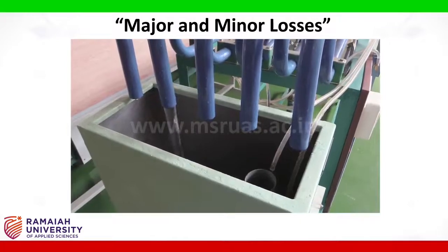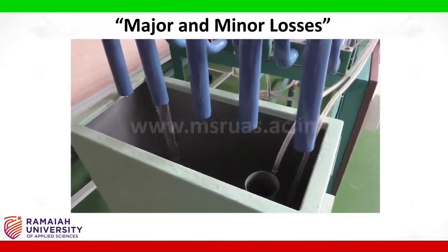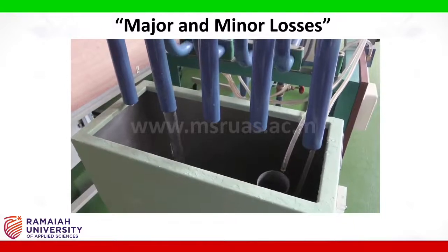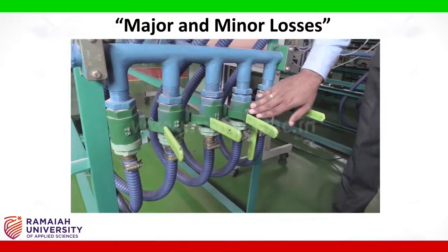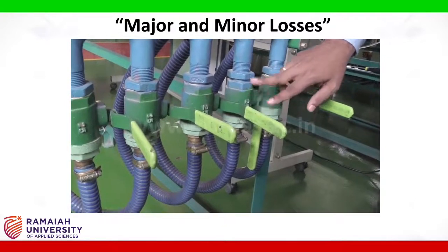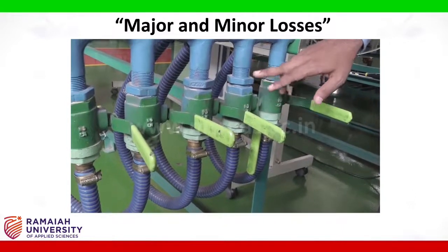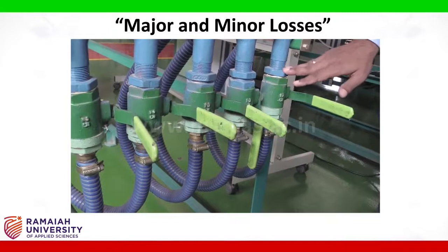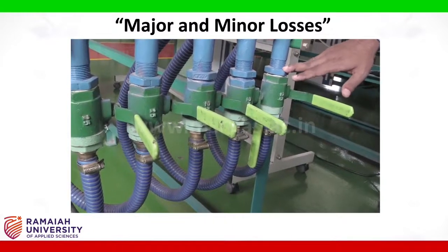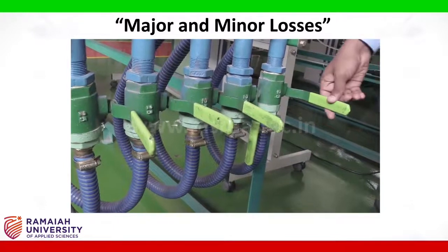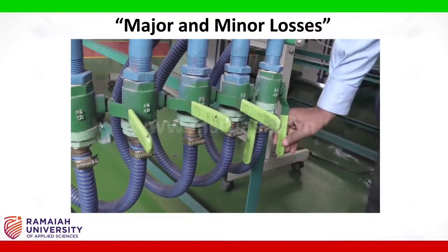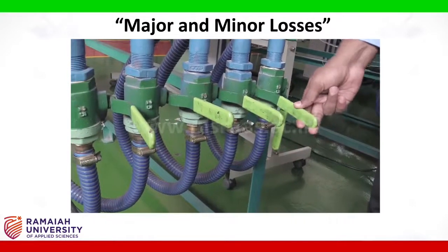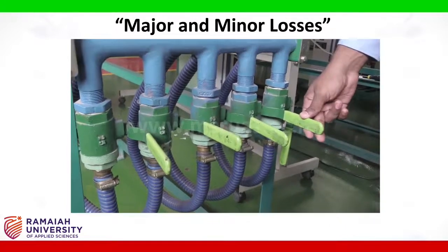Now, the water is being collected in the collecting tank. Here, we shall calculate the discharge flowing through the 4th pipeline. The sudden expansion, sudden contraction and the bends are present in the 4th pipeline, whereas the non-return valve, the gate valve and the wheel valve are present in the 5th pipeline. In order to allow the water to flow through these valves, we shall open the final and the 5th pipeline's ball valve in the main header and close the valve containing bends and sudden contraction and expansion.